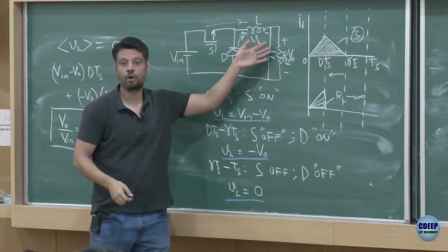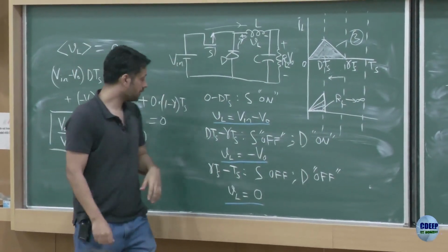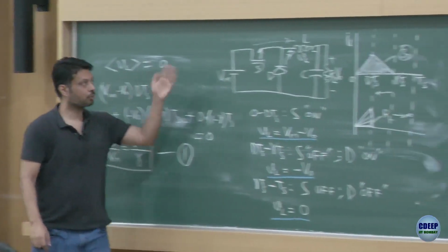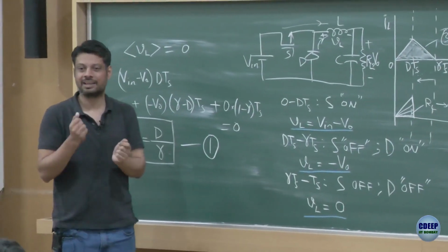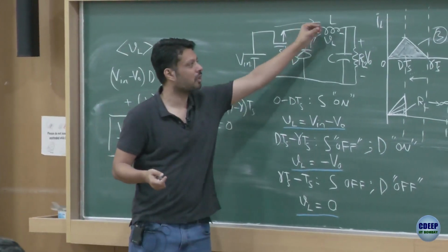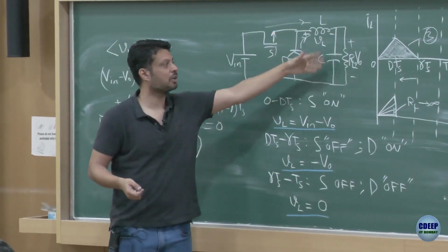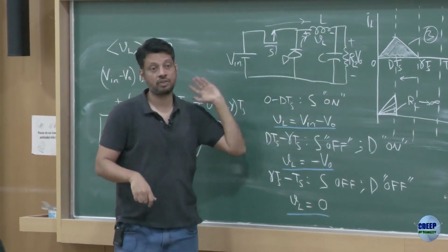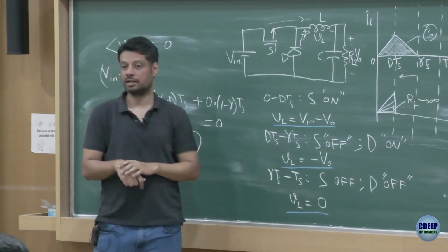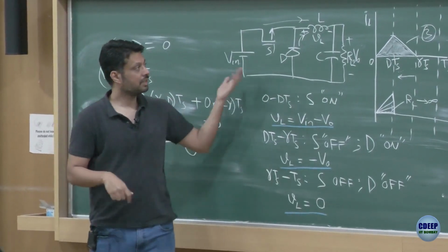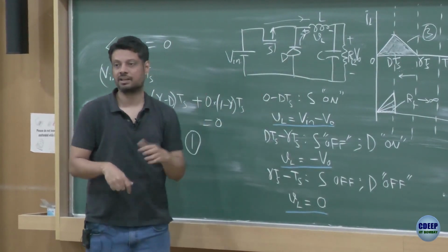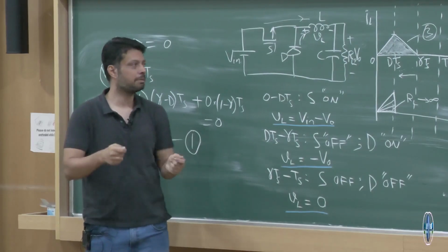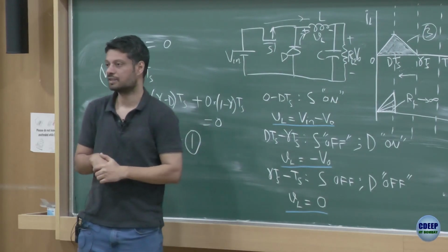That means this voltage would be almost equal to this voltage, your gamma would be almost equal to D, your input voltage will be almost equal to output voltage. When you close the switch, nothing will happen, maybe slightly current will rise. When you turn it off, nothing will happen, that small current will just reduce, if at all you have very close to infinite resistance at the output. And that's happening because your output voltage is now dependent on gamma or dependent on RL, right. So if your RL tends towards infinity, this would give you almost the same voltage as that of the input supply, irrespective of the duty cycle, right. I mean, it will of course change a little bit with duty cycle, but more or less it will give you the same output voltage as input voltage.